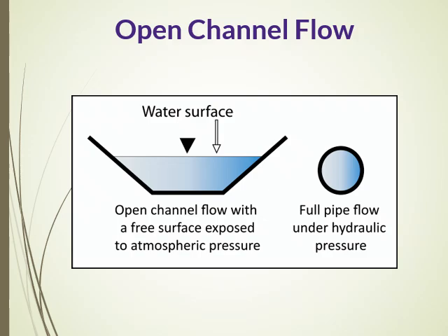What is open channel? It refers to the movement of liquid with a free surface exposed to the atmosphere. This happens when the flows are driven mainly by gravity, not by pressure differences. Water in a river, canal, drain, or natural stream all behave as an open channel. The channel may be rectangular, triangular, trapezoidal, or circular. The bed slope, the surface roughness, and the depth of flow influence how the water moves from one place to another.